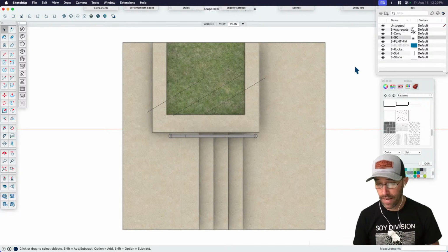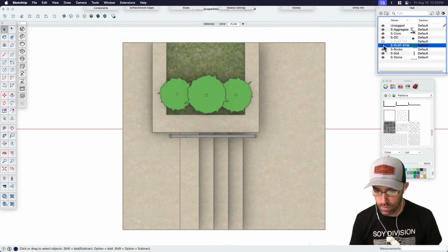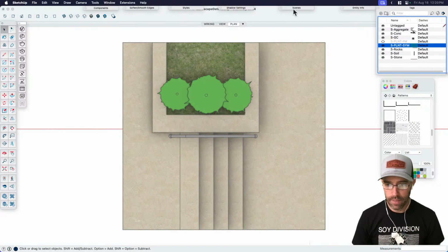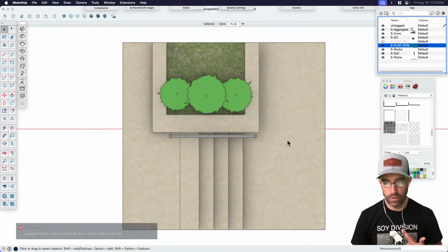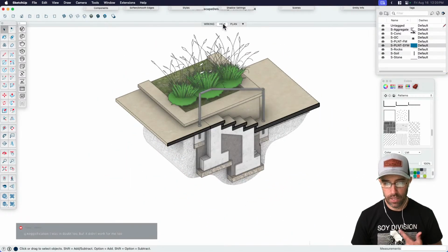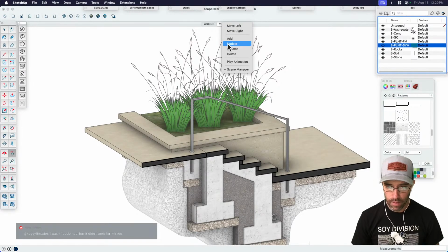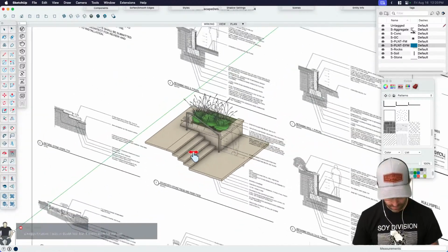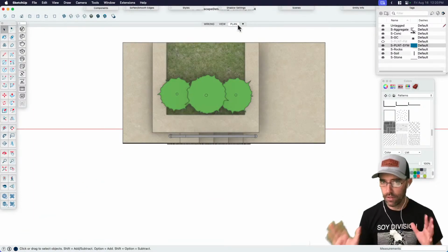Everything else, as far as tags and styles, can be done afterwards. So I'm going to switch my plant symbols, update this, and double check my scenes. I'm going to make sure that my camera location is saved for my plan view. You'll notice that the other ones don't have camera location. This was my section cut, where I want to make sure I turn my plant symbol off. And this was my working scene, which just has all of my notes and things, really meant for as we build this up. I think that's all I need. Everything else I think I can do in layout.